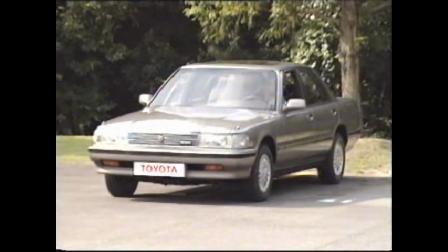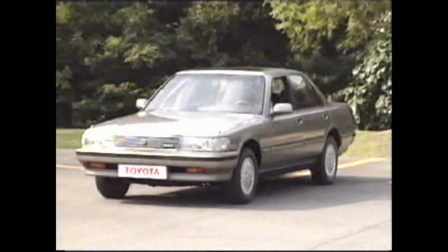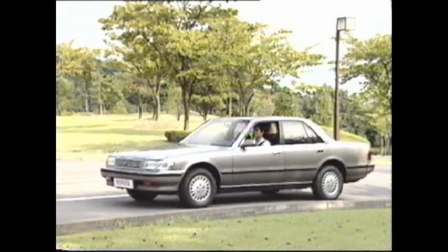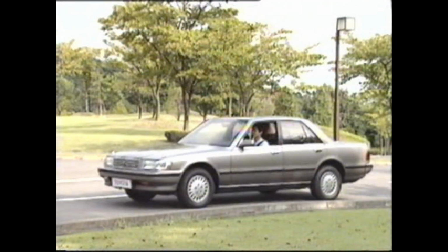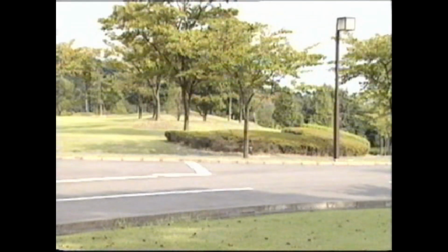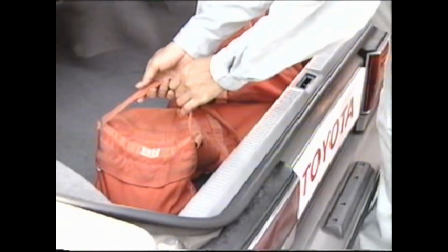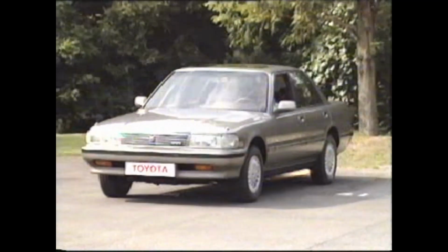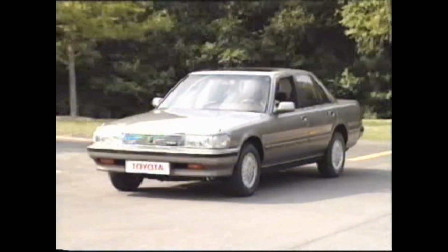This is where the driver feels intermittent vibrations and is shaken back and forth when the clutch is engaged. Or the vehicle suddenly moves forward when the clutch is partially engaged. In both cases, it may be concluded that there is a clutch engaging problem. Such conditions may not be noticeable in ordinary driving, but will become more noticeable when the car is started on an uphill grade or with a heavy load.